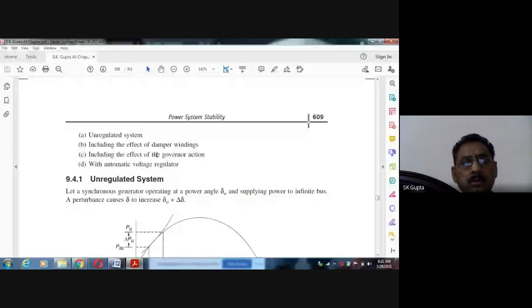That's why we may consider a small disturbance, 10% or 15%, and we know whenever there is a change in load, the governor also comes into the picture. Means initially, if say load becomes 100 to 110 megawatt, then the governor senses and allows additional fuel to flow so that it can be covered. Means additional load can be taken care of by the extra fuel entry in the turbine.